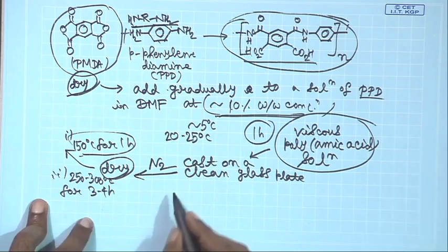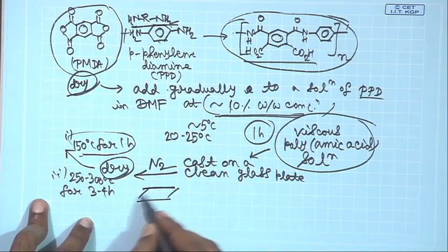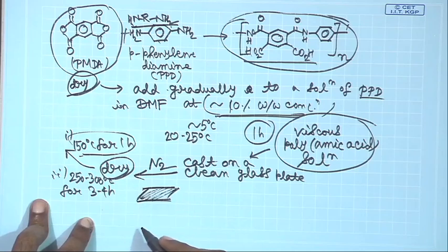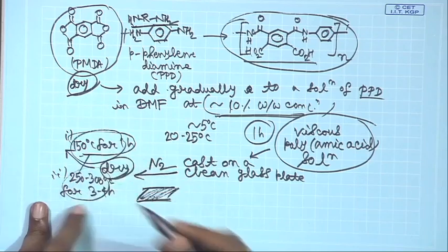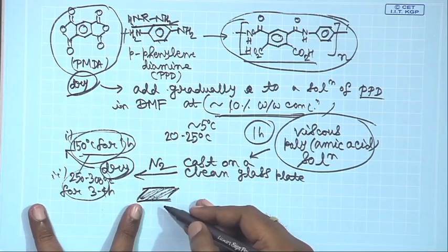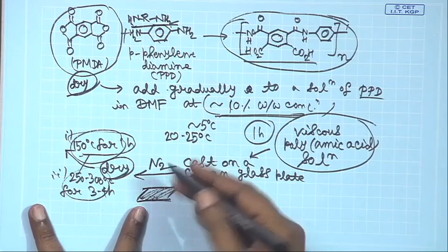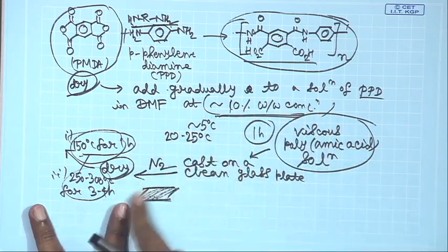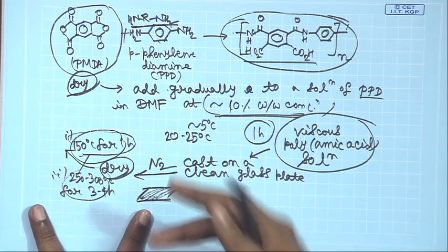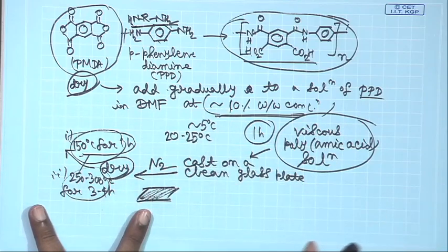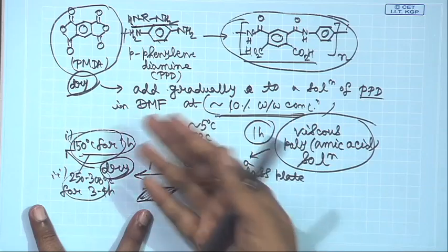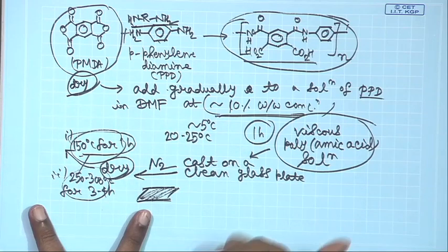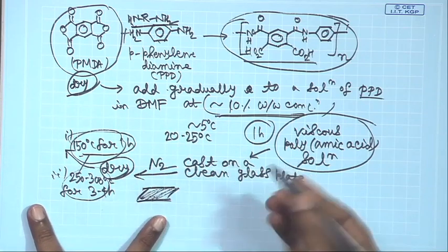That is the idea. So, what you have here is your glass plate on which you have this film of polyimide. Now, you cool it down, because the process has been done at high temperature and cyclization has occurred. Then you immerse this glass plate in a water bath, and this film will just detach. You take out this film with a tweezer maybe, and then you dry it in air or heat it further.